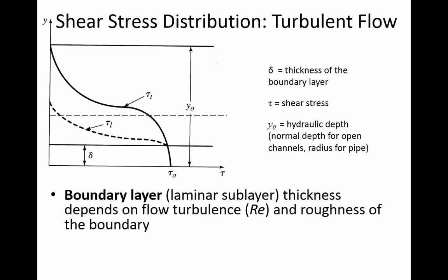So let's go back to when velocity was low. If velocity is low, then it's slow in the center, but it's also really slow around the edge. Near the edge of the pipe, the velocity is really slow, and the Reynolds number in there might be less than 2,000 even. You could have laminar conditions in that boundary layer.